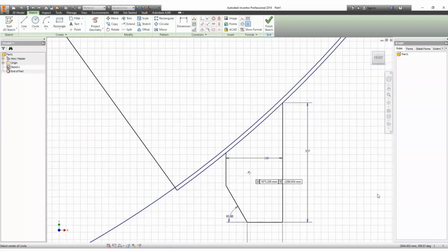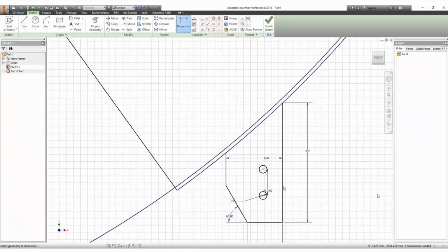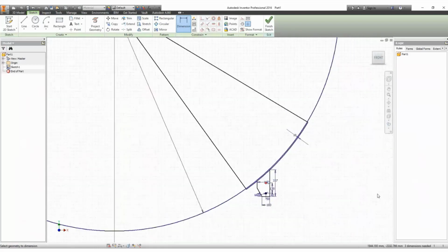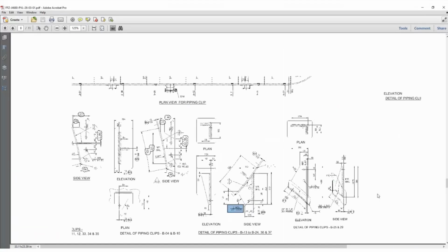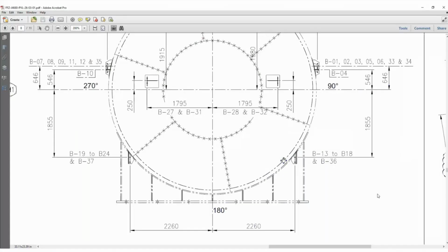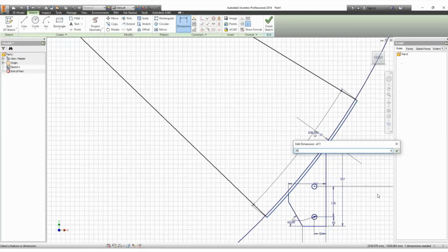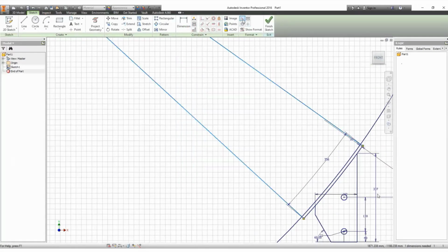And let's add the holes inside this plate as a 2D sketch. We are doing a 2D sketch only now. After that, we will convert it to a 3D model and add it finally to the vessel assembly. Now, let's define the location of this ellipse from the vessel center line. Define the wear plate width.